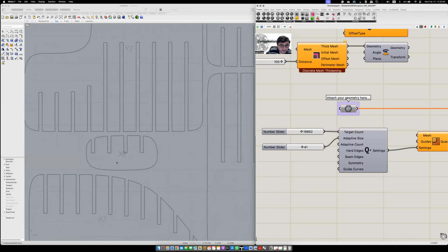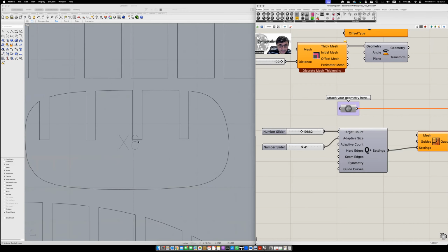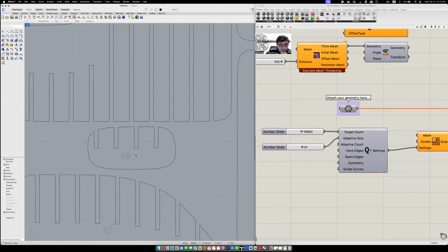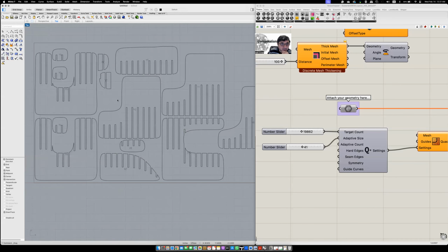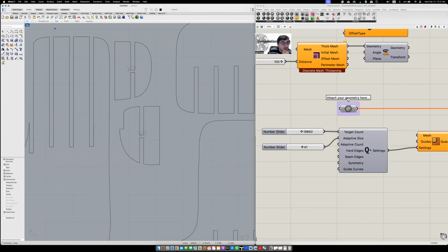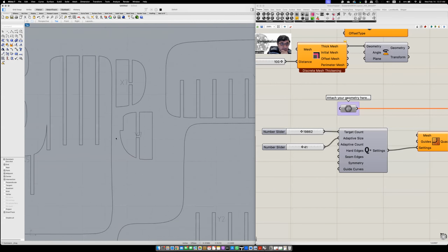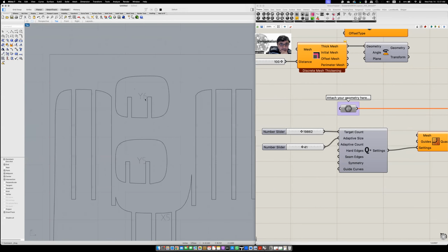One is that if you zoom in, this X8 profile is intersecting with the profile corner. So we clear this out. We move them away from the profile cuts. Right, so there is this one. If your grid, when you select an object, if you are moving and it doesn't sit in a proper place, then you can turn on this grid snap and then it will be free to move. This will be much easier to move around.